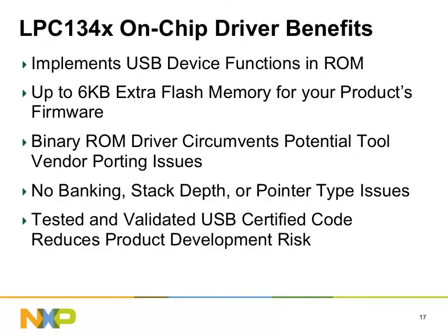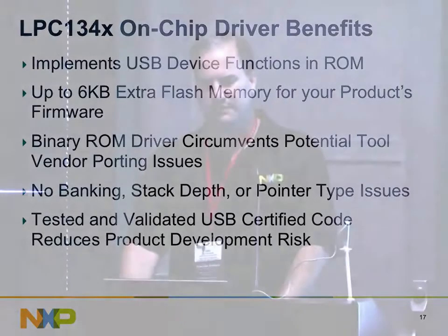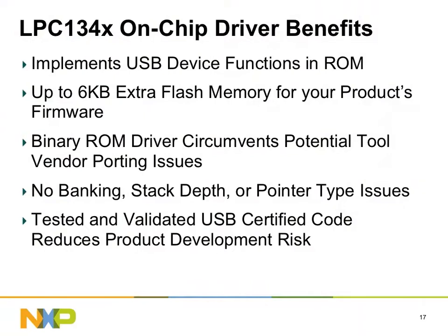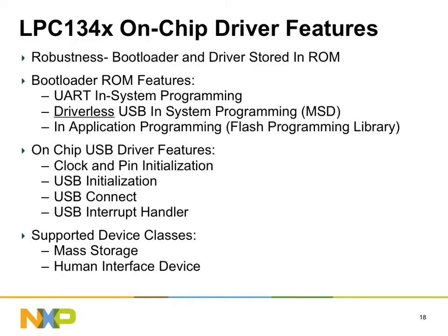So these are the things that this chip addresses. It implements the USB device functions in ROM, and this frees up 6K of extra memory, so that you can put that into your product. A binary ROM driver circumvents potential tool vendor porting issues, of course. And it's tested and it's certified and it works properly. So these are the on-chip driver features. It's a standard ARM-based SoC, but with all the USB driver functions in ROM.